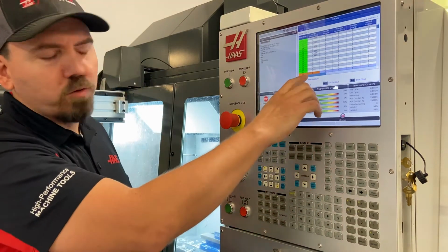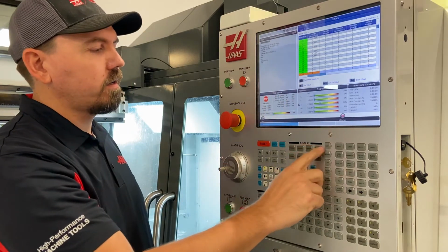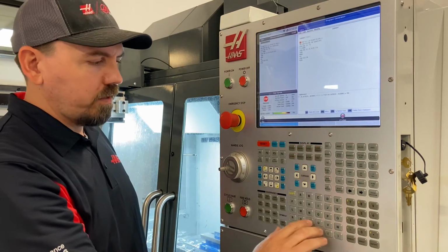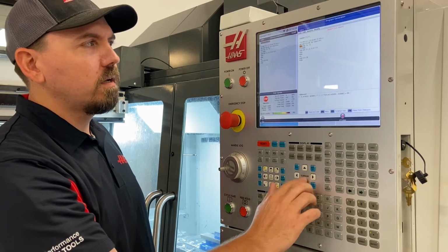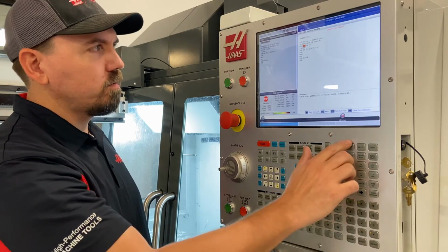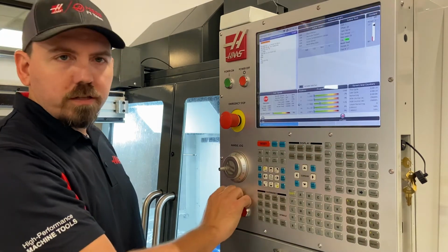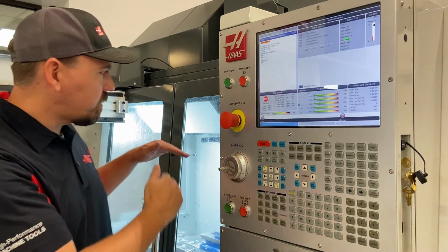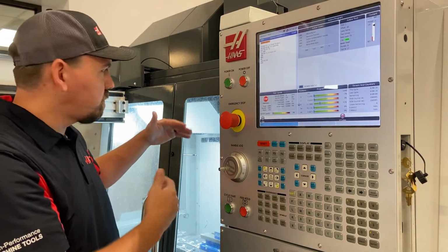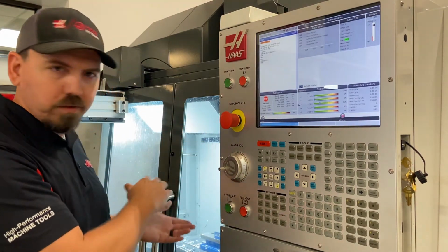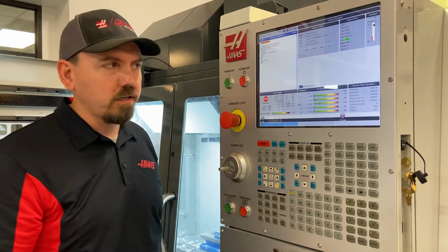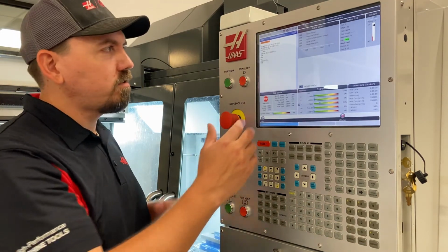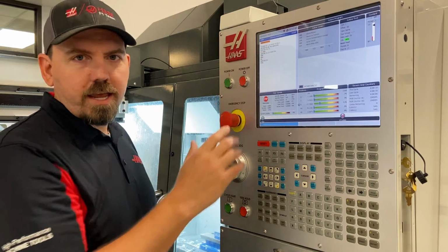something down here. Offset 22, I have a zero value in here. So if I put tool 22, offset 22, alter, and run this program, the machine's going to attempt to run with the zero value, which is the spindle face basically. It's going to try to face my part. Not good. The workaround for this is to alias the M6 command.